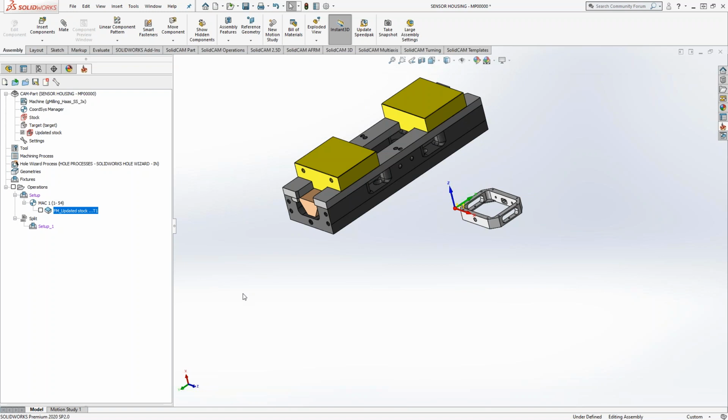Correct. The I number of fixtures is only in the G code, not in the simulation. Whereas with the transform coordinate system, you can see that. You have to set up the coordinate systems inside this part file anyway, so you'll see it in your simulation. If you set up multiple stocks, multiple targets, and all that, you can actually see the material being removed.